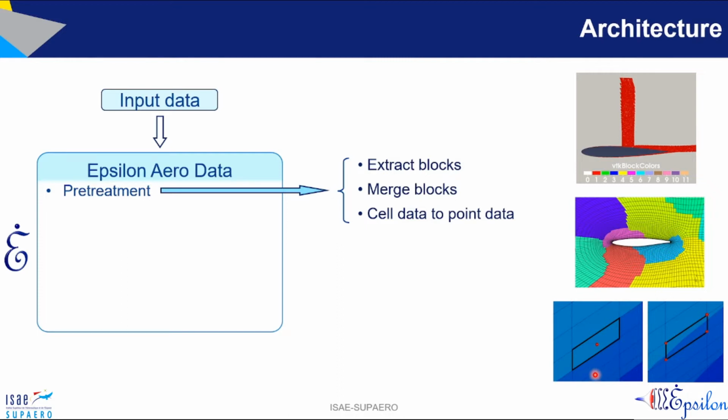It's quite safe for us to assume point-based data, but in some specific cases where accuracy will be compromised, we'll see that in Epsilon Nearfield, for example, we retain the cell data. Or if your input CFD data is already point-based, it will convert it to a cell-based solution.